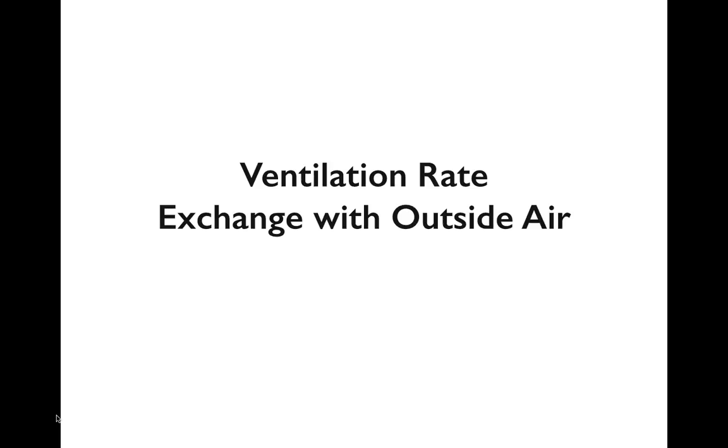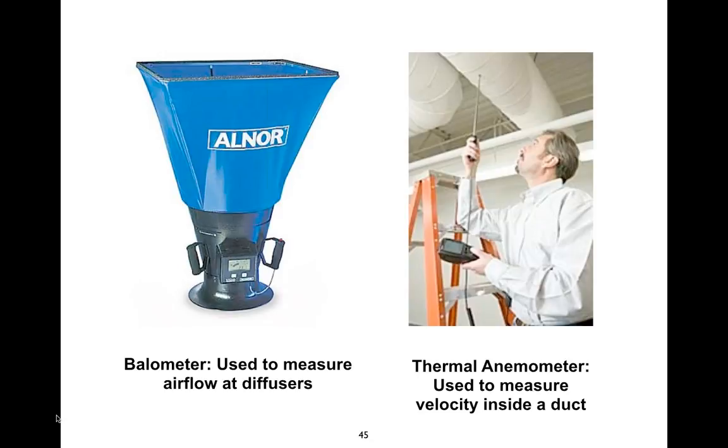The first thing we do is evaluate the ventilation. First of all, we inspect the HVAC equipment, so we get an understanding of how it works. How is it supposed to work? Is that reasonable? Is the equipment working properly? Is it in good condition? Is there stuff that's not working, like dampers not opening, outside air dampers not opening, and so on?